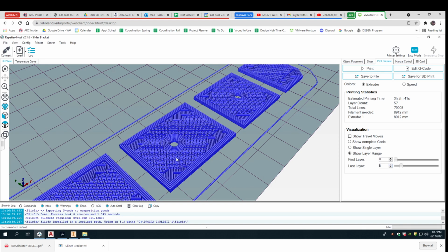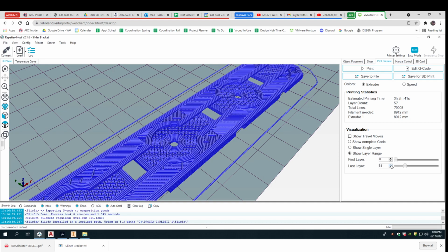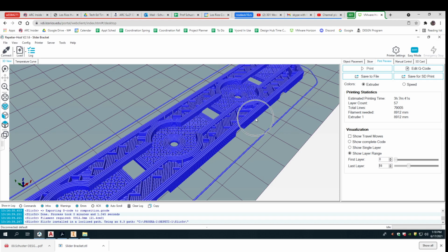And this is the Hilbert curve. And those are really good because long, thin strings like you see here warp. Okay, it's a thermoplastic, so when it goes down hot, it's all stretched out, and as it cools off, it shrinks and it tries to pull up. And that's why I have these little gaps. And you'll see that in a minute. Now I've filled in those gaps, but these have had time to really grab on and sit down tight. If you have a heated bed, that is not an issue.